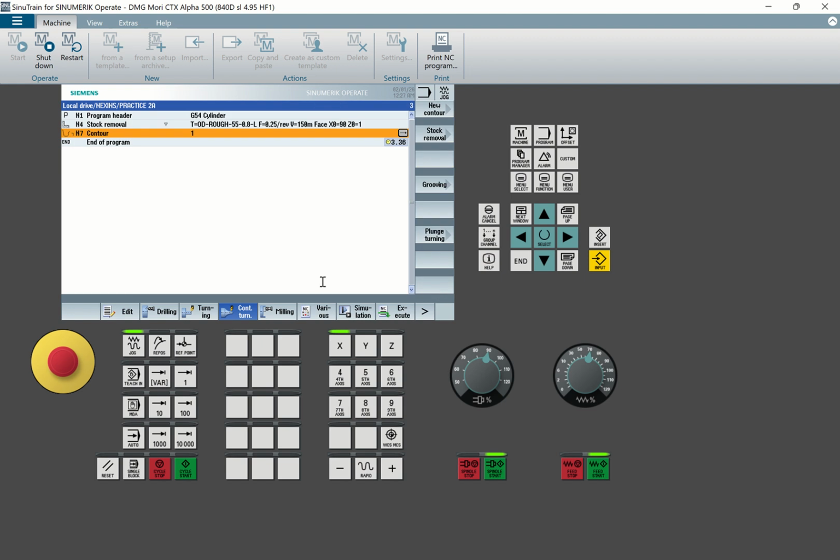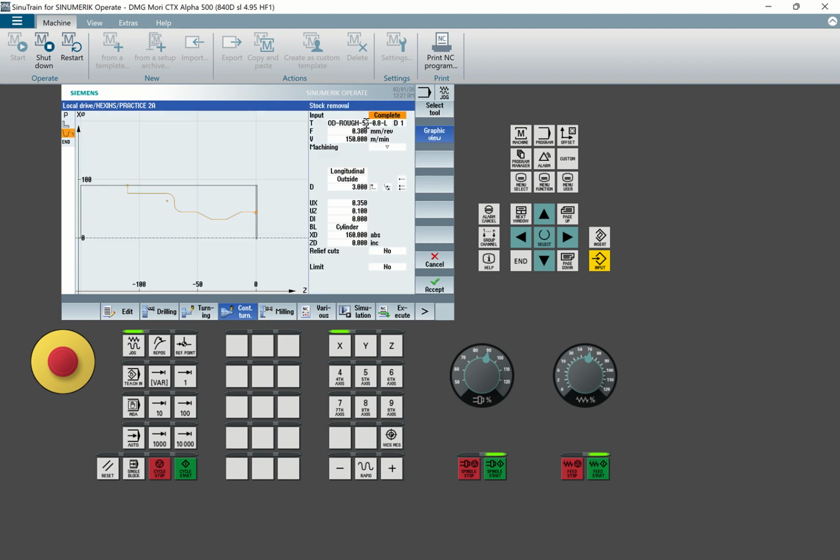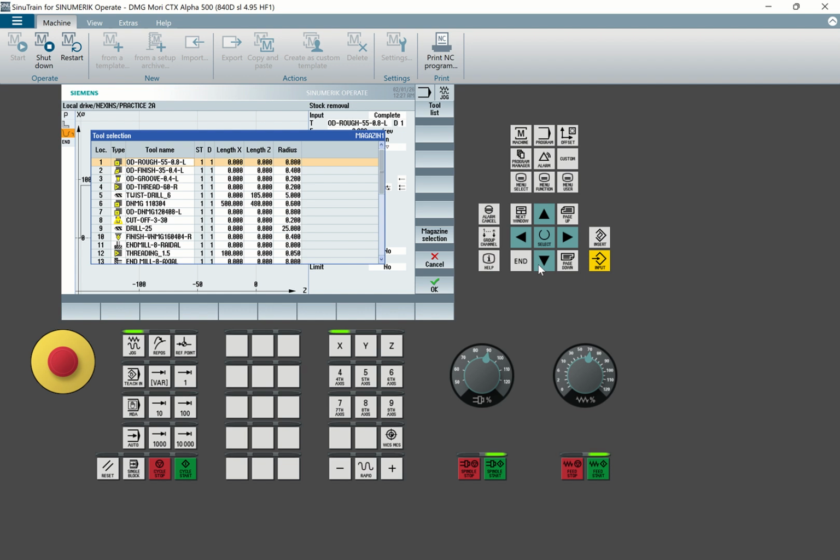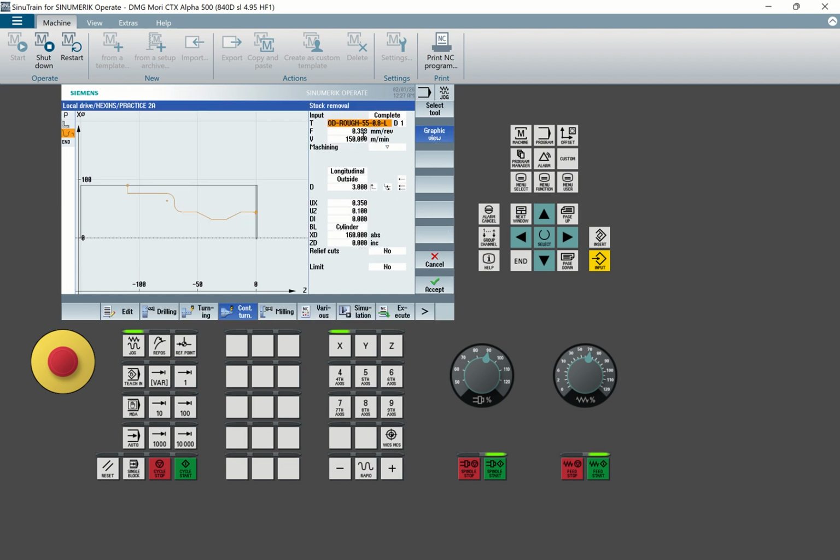Then from there accept. Once you accept, now come here to the other contour, below new contour, click on new stock removal, check that you have the correct tool for OD turning. Roughing, can put 0.25 depending on the material, can put minus 140 depending on the material. I'm doing roughing and finishing at the same time, so this means I'm using a different tool. Then I'm doing outside diameter. My diameter here was 90 for the stock. Then I can say accept. Don't have any undercut here, I say accept.